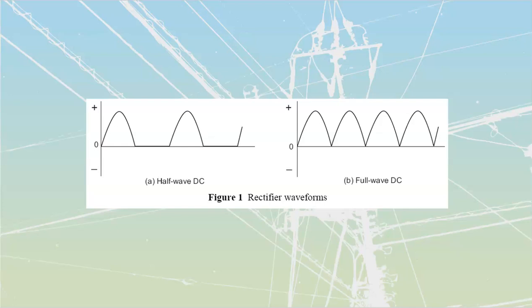Two main types of waveforms that we are going to have. We've got half wave. Half wave is going to have cut away and discarded half of the wave, right? What we see for a regular AC sine wave, we're cutting away and getting rid of all of that negative side of it. So that's going to be half wave rectified DC. And then full wave is going to be taking those halves that we would have thrown away before and then flipping them, sending them to the top over here, just through some sneaky connections and utilizing our actual components.